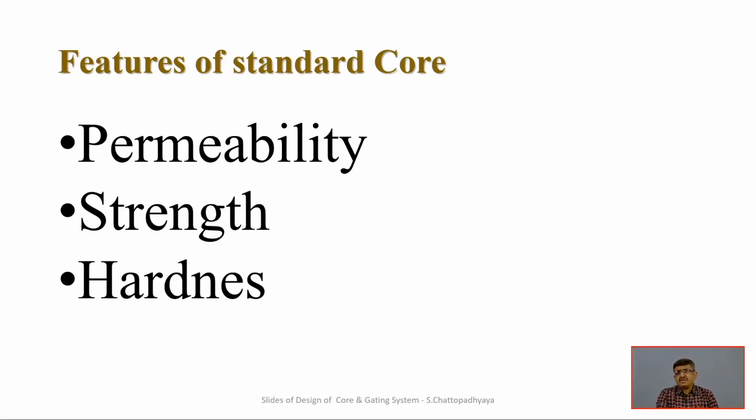And what are the features of the standard core? As usual, the features of the moulding sand. The first one is permeability. The escape route for those entrapped gases has to be provided. Otherwise, they will remain there and will be the cause of concern of defective casting.